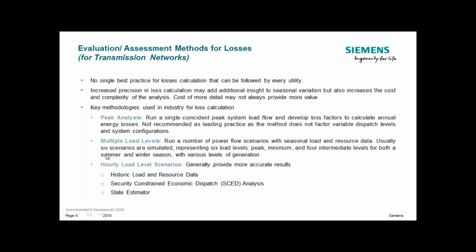It's not online, but it's more accurate, close to online simulations. Then you can run the load flow and short circuit calculations and see how much it varies. At the end, you will have a pattern of each individual. You can use it on the grid, where you have a smart meter, and you have a pattern available, hourly or every 10 minutes, whatever the historian has available.